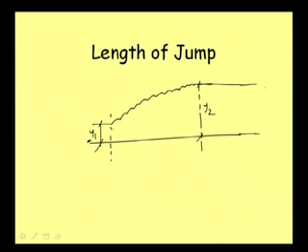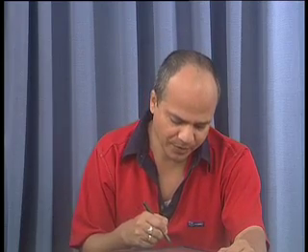Then, if that initial point of the hydraulic jump is known and it is a rectangular channel, we can use the formula y2 by y1 is equal to half of root over 1 plus 8 F1 square minus 1. So that formula we can apply, and that way we can find the value of y2.